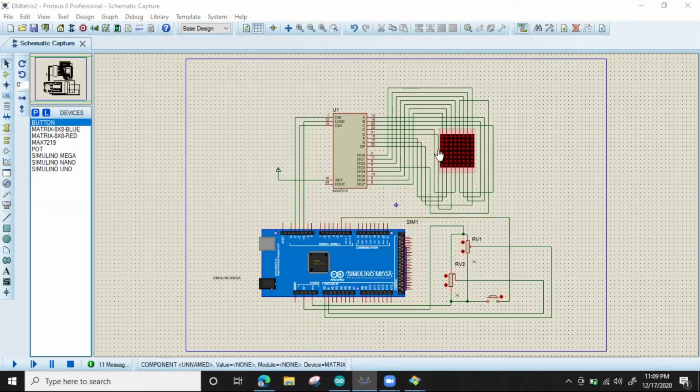We are using a MAX7219 8x8 LED module. The MAX7219 is an IC designed to control an 8x8 LED matrix. The MAX7219 input interface is a 16-bit serial input shift register. The first 8 bits define a command while the second 8 bits define the data for that command.